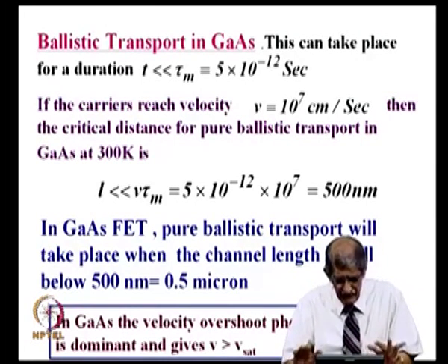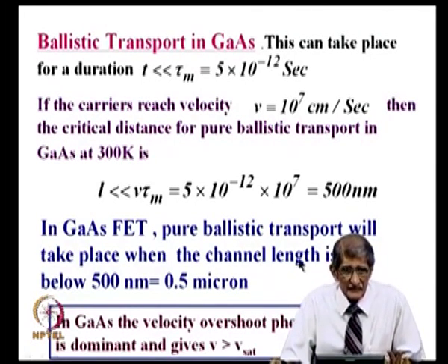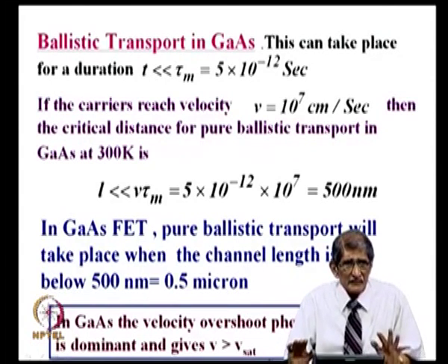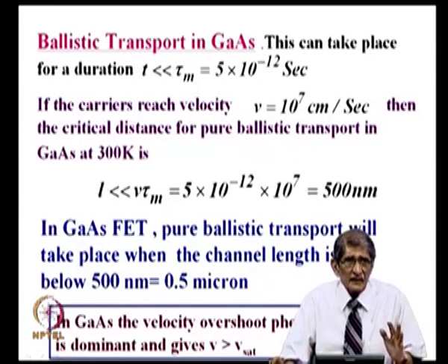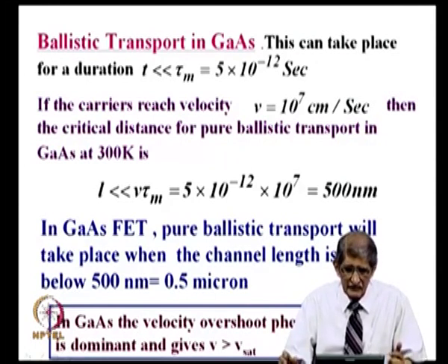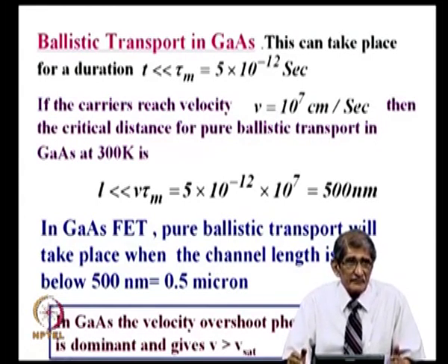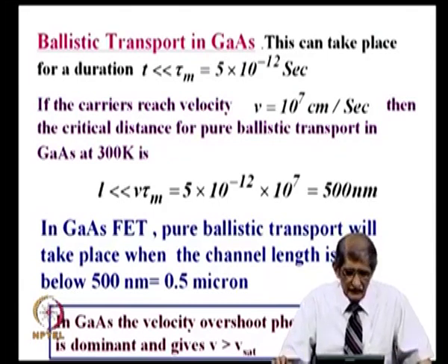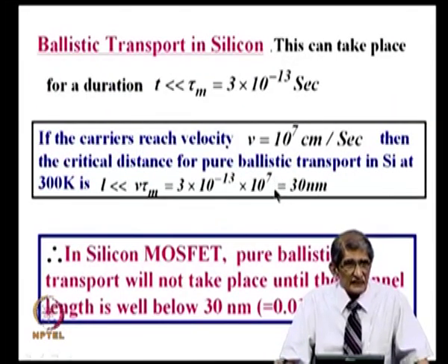I have put it very briefly without going into details. The meaning is, sudden transient effects in gallium arsenide lead to that overshoot effect, because that has at least a few picoseconds of time, whereas in silicon you do not see that, because it is much shorter than a picosecond, about 0.3 picoseconds.